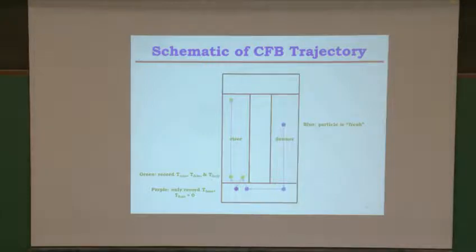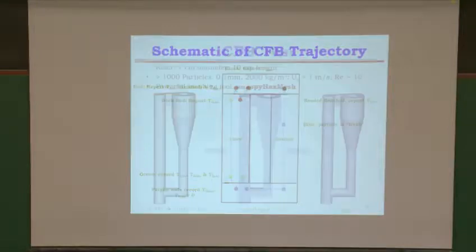It can go up the riser, it's still in, so we want to count that. Now it's out of the riser. Now it goes back in, so we can start counting again. And then it's back out again. So we can keep track of where all these particles are, so that gives us a way of marking what is the true RTD in each of those sections. We're going to record that as we do the simulation.